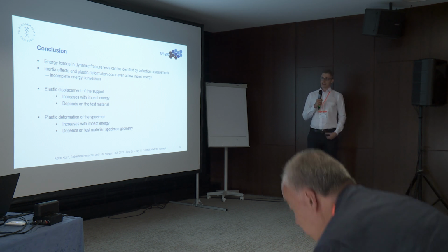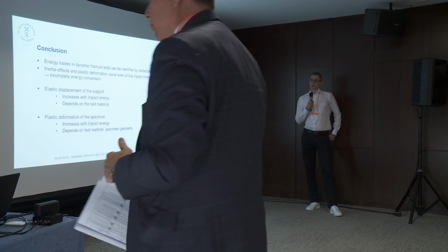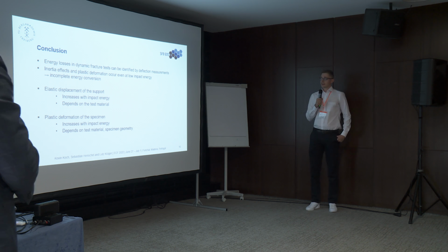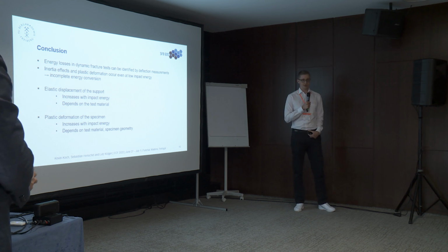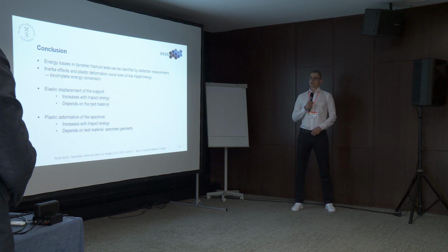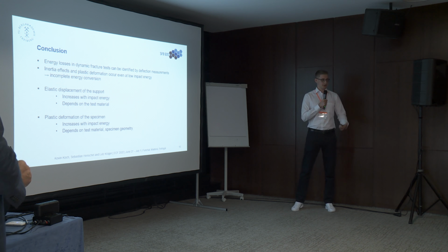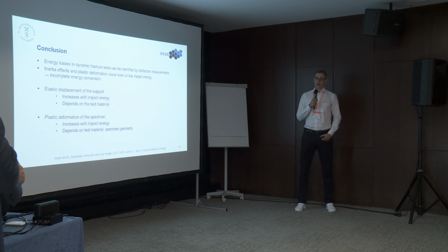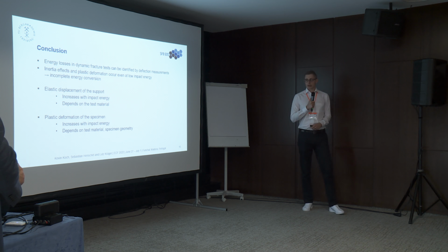To conclude my presentation, we observed that energy losses in dynamic fracture toughness tests could be investigated and identified by deflection measurements with a laser. And these inertia effects and also the plastic displacements occurred at low impact energies, and they led to an incomplete energy conversion. Our first main factor was the elastic displacement of the support, which increased with impact energy and also depends on the test material.